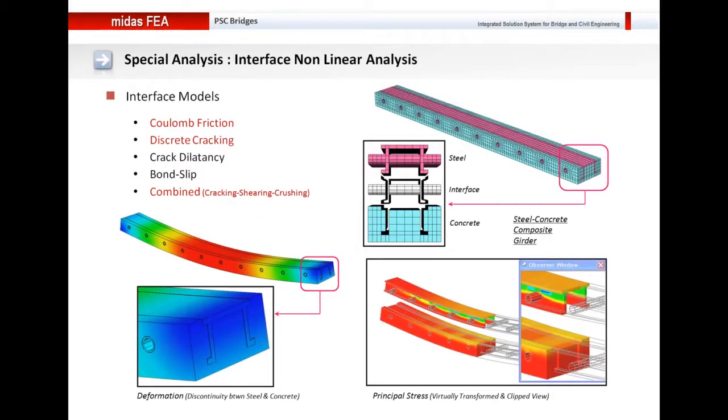You can also use Midas FEA to perform interface nonlinear analysis. As I mentioned earlier, we have different interface models, as you can see here, and modeling the interfaces is pretty simple in Midas FEA. All you gotta do is model the solid, and Midas FEA will automatically extract the outer shell for you, where you can define the interface parameter. So this is how I've created the interface parameters there.